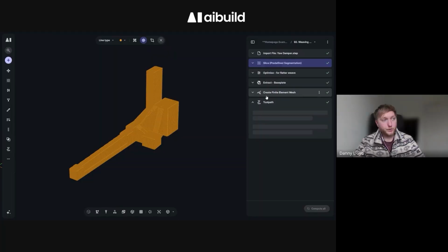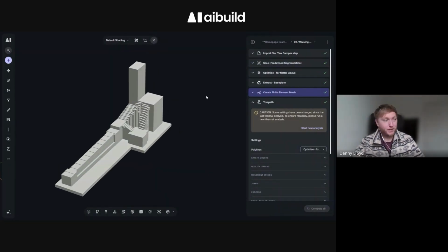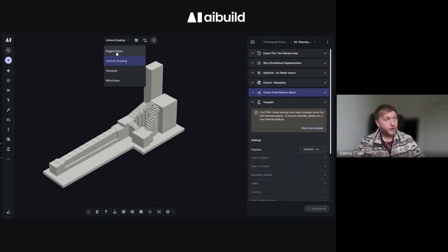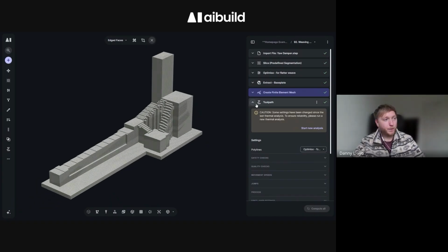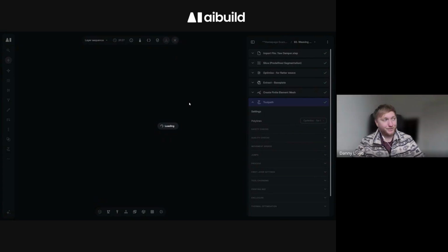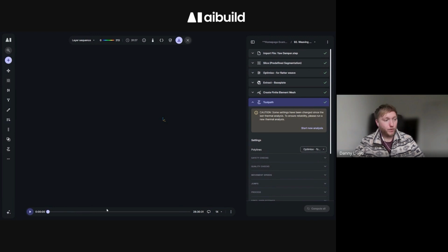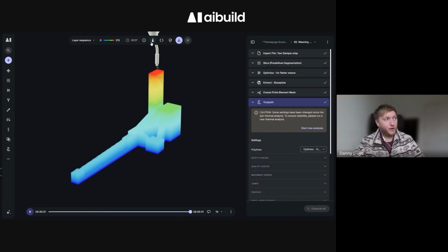And this one as well, I also took the liberty of creating a finite element analysis. So we created the finite element mesh from the toolpath, which is a unique feature of Aibuild. We don't do it from the CAD file. The CAD and the mesh are two different things, and so is the toolpath, which is actually what should be analyzed. Exactly. If we analyze the CAD file, it will show us one thing, but really we are weaving the whole part, right? We've got a strategy that's pretty different to the CAD file.